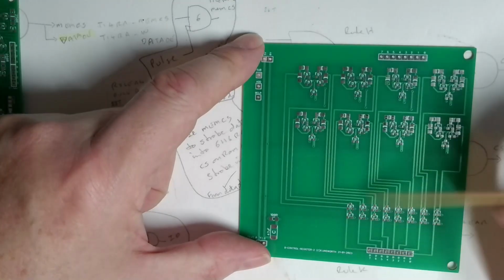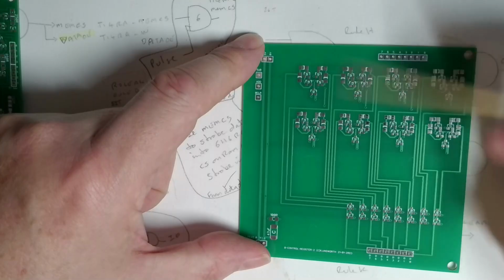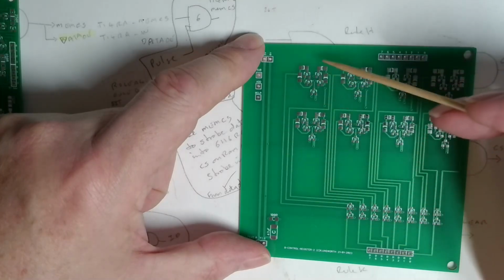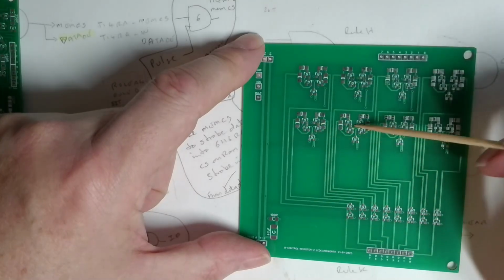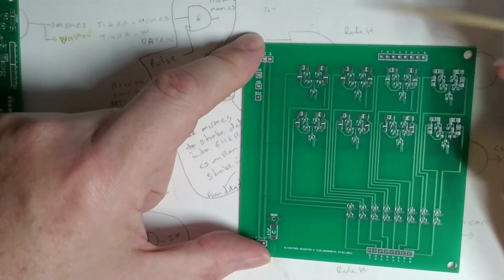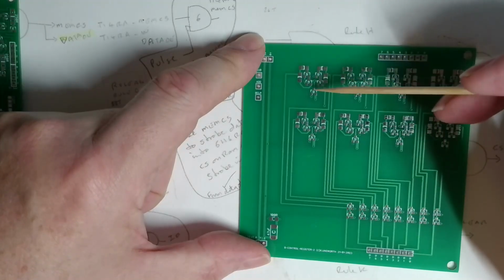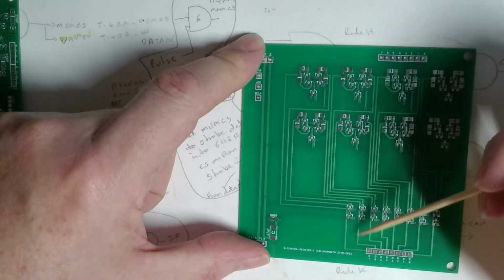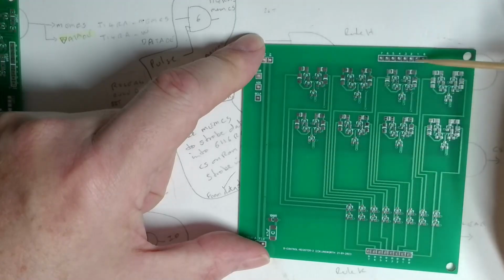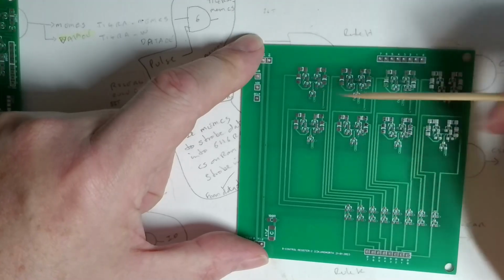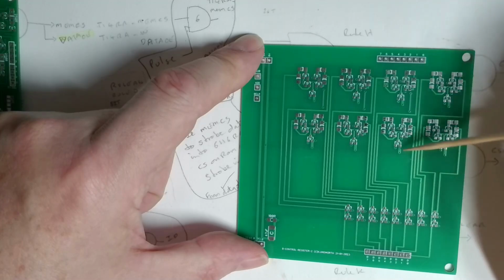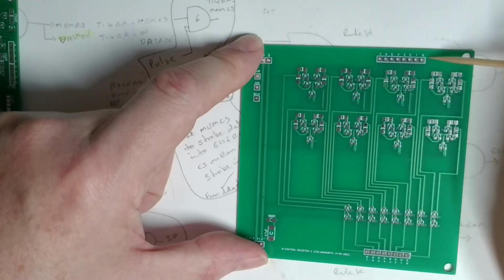So we've got 16 signals going up rather than 8. The 8 normal ones come straight through, and each one of these is one bit of the switching circuits. So here we'd have a direct in, or the inverted signal switched out to the B register, or these are the transistors at the bottom, where you're switching it down to 0 volts to give you 0 out there.